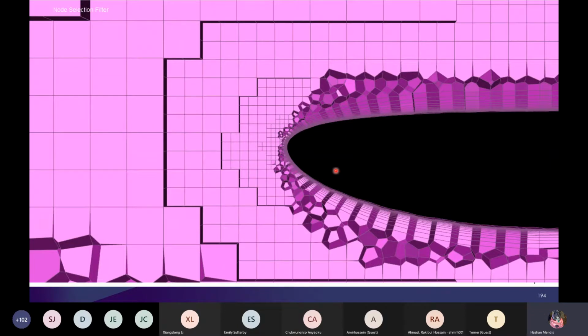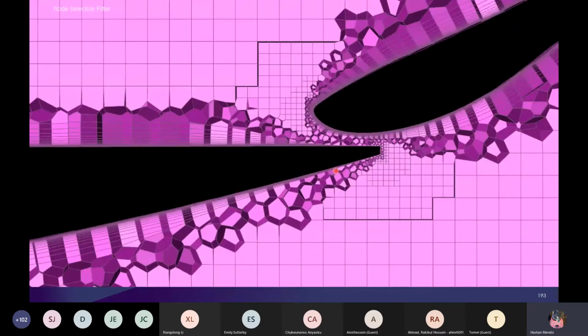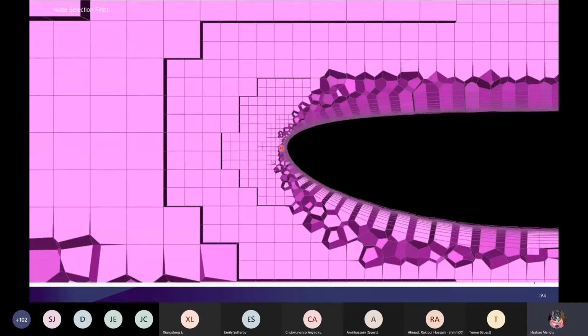How do you determine what the minimum size is? So generally, like I said before, sometimes it can come down to trial and error. Looking at this, you can get a general idea, depending on the size, of how many elements you might want around there to capture the curvature, right? If I just had one big element, that might not be appropriate. So, 3 to 4 might be a good place to start. And then what I'll generally do is have a look at the actual results, right? So are the results telling me that I need to maybe refine around specific regions?